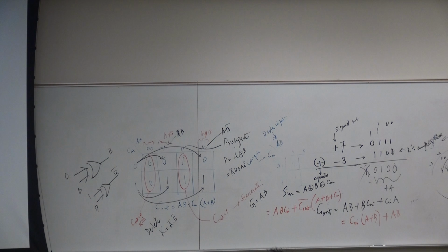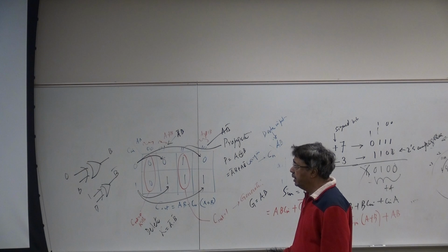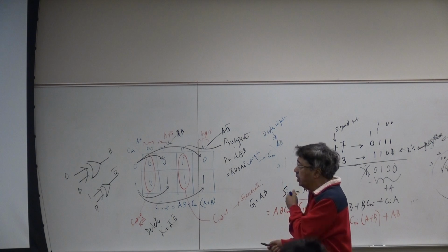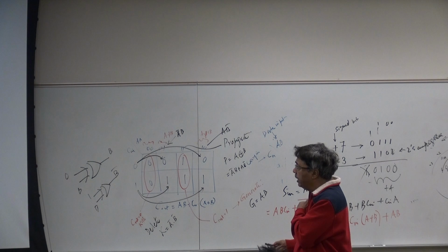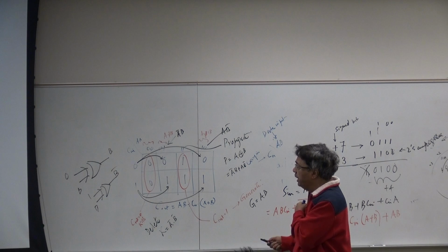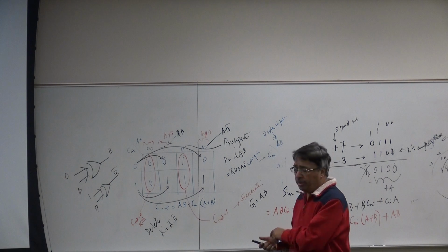For the ripple carry adder, we can find the delay is the delay through n-1 stages of the carry. So this carry has to go through all over here, and after the carry comes over here, then the sum is generated. So the question is whether this is generated faster or this is generated faster. That's why we take the maximum value of the carry out and the sum. So this is the expression for the ripple carry adder.